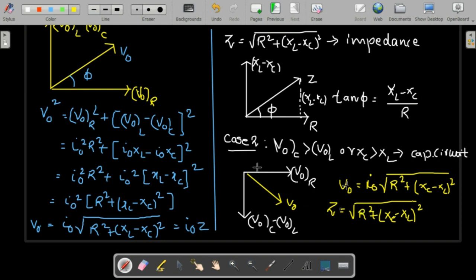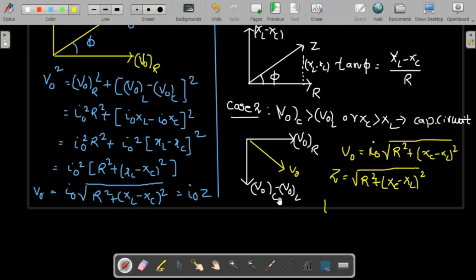And if you draw your phasor diagram for the reactance, the Z or the tan phi will also more or less be there. You can also find this particular case, so that is also possible. Let me just complete this. So if we take out tan phi, that was XL minus XC, here it will be XC minus XL, whichever is greater will be at the front to keep it positive.